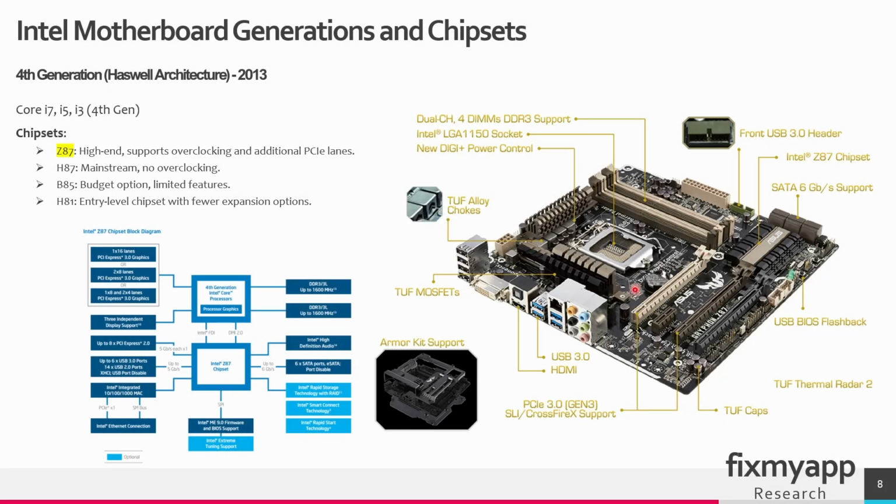This is a 4th generation motherboard that supports different chipsets. So this chipset implements these functionalities. But if you look at the physical layout of the motherboard, the location is still the same. So these are the back end connectors. These are the PCIe 3.0 slot. So this is the high speed slot that will go to the CPU. Then we have the lower speed slots.